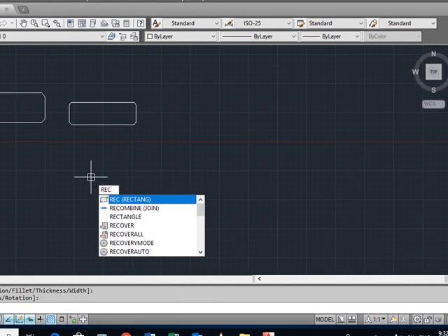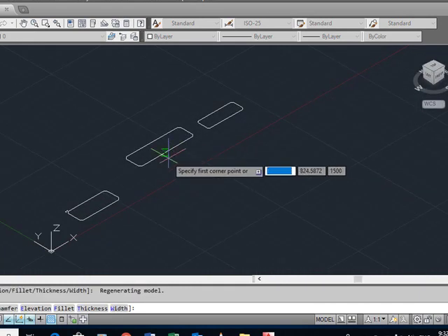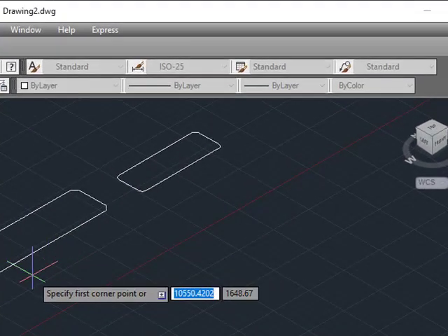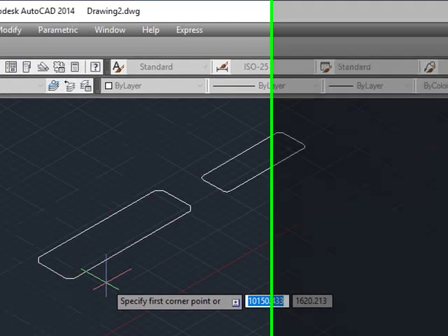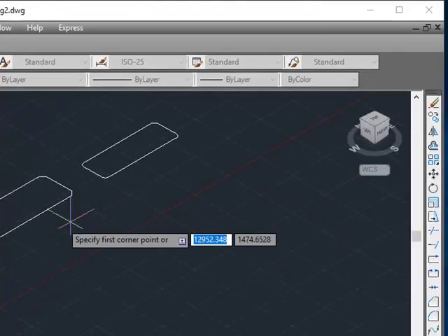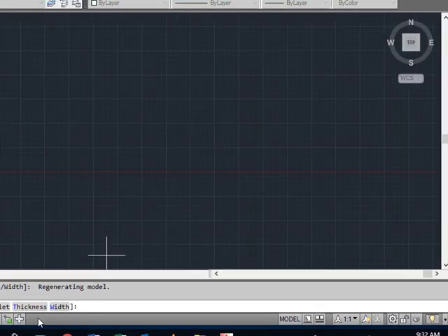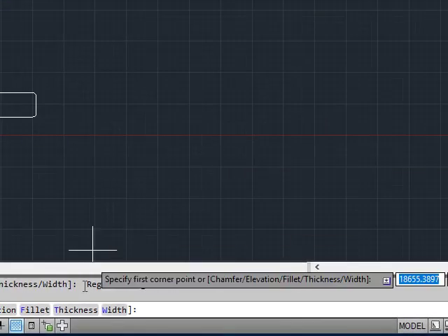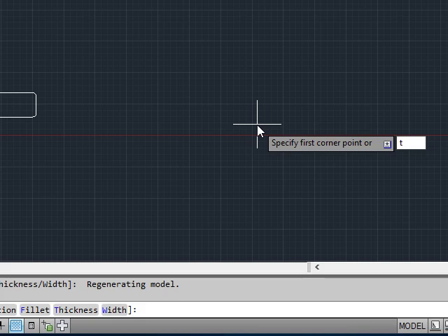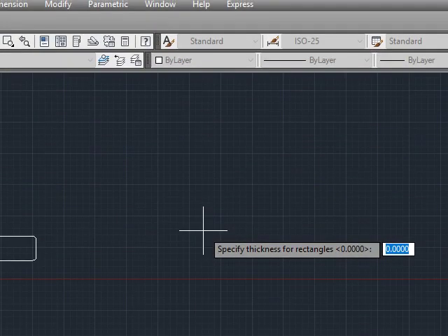And the next one is rectangle thickness. As you see here, I told you it's a table, so this table does not have any thickness. If you want to make a thickness for this, just come here, type the T because only the T is colored below. T. How much should be the thickness? For example, around 10 cm or 15 cm.